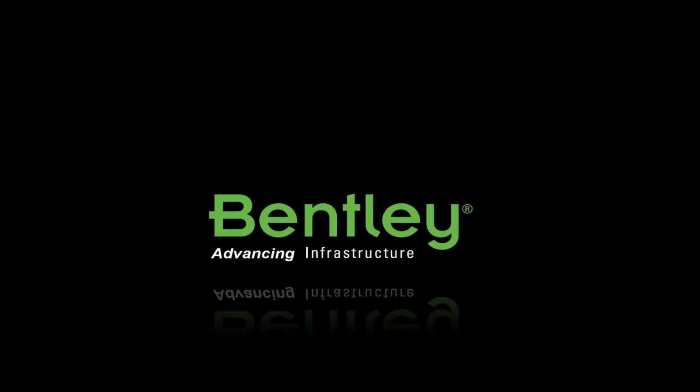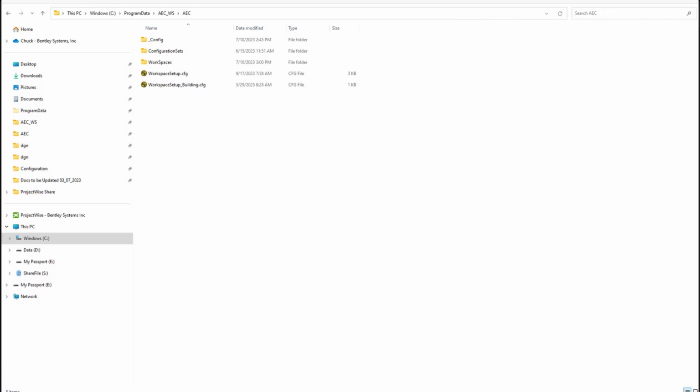To begin to explain what a workspace is, we need to understand the fundamental concepts of what is under the hood, if you will. A workspace used with MicroStation or some of the other products like OpenRoads or OpenBuildings or ProStructures that the Army Corps implements is simply a culmination of folders and configuration files that contain individual settings. Let's take, for example, levels.